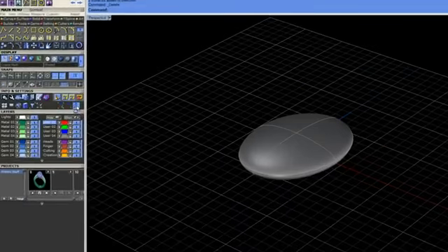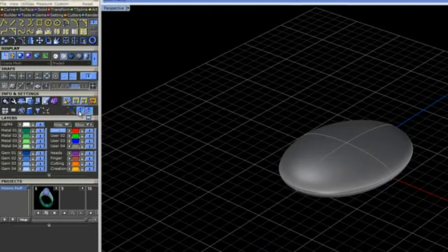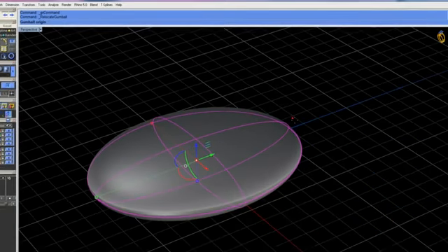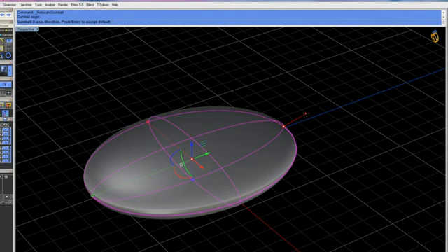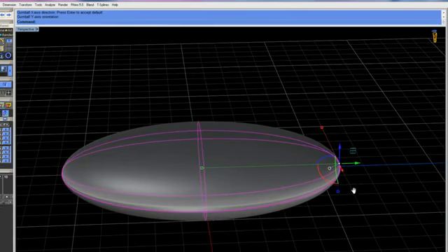Okay, as we continue on here into our info and settings, we have two additional icons. The next icon here within our info and settings also has to do with the gumball. This one right here, if I click on it, will allow me to relocate the gumball. So it's going to ask for the new origin point, so I can snap right to an end. And then in my command line here, it's going to ask me for the X direction, so I can hold down Shift, and then I can hold down Shift again to give it its Y orientation. So now I've set up my gumball to be right there on the end.